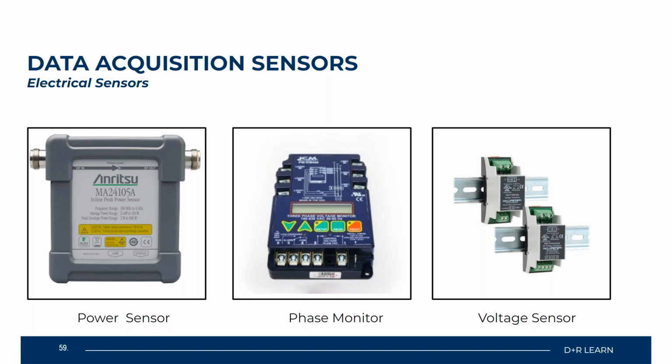Now, if you have a phase monitor attached to that system, it will alert you immediately. In the field, if you know an HVAC technician that has done a lot of work, a lot of times, if they're like me and have done this for some time now, they may tell you that they can hear when you have a phase reversal of a system. I know for me, I can hear it. So whenever a compressor is running backwards, I can tell you immediately that it's running backwards.